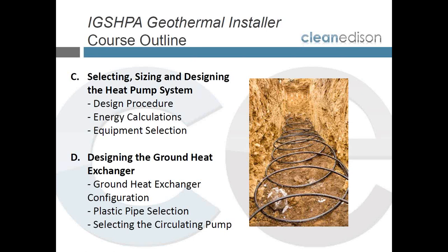We do energy calculations to show what the annual heating and cooling loads and costs will be, and we discuss equipment selection and why we select heat pumps based on their heating capacity and cooling capacity.